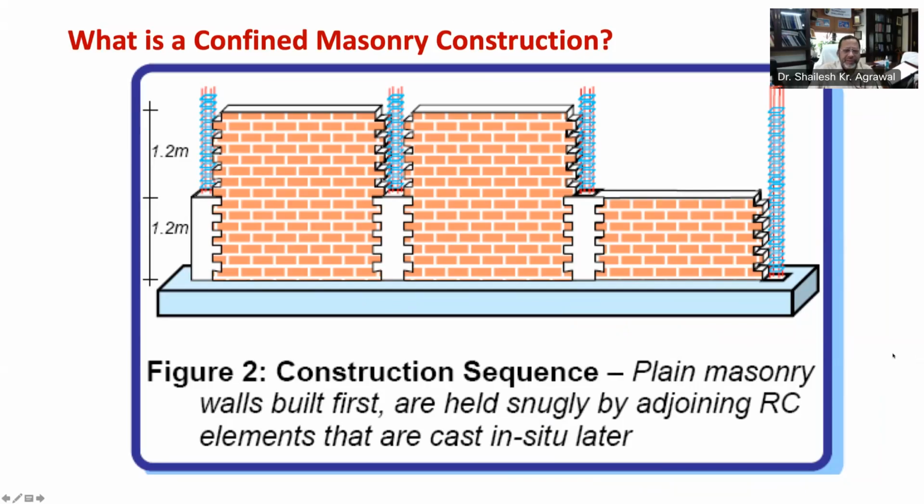The concept of confined masonry wall construction, confined with wooden elements, has been in use for centuries in many earthquake-prone regions along the Alpine Himalayan belt. For example, in the Kashmir Valley of India, Dhajji Diwari, a local vernacular construction, consists of large masonry walls broken into smaller panels with wood verticals, horizontals, and diagonals. These houses showed excellent performance in many past earthquakes and helped avoid loss of life. These houses have simple architectural design, good quality materials, and good quality of construction.